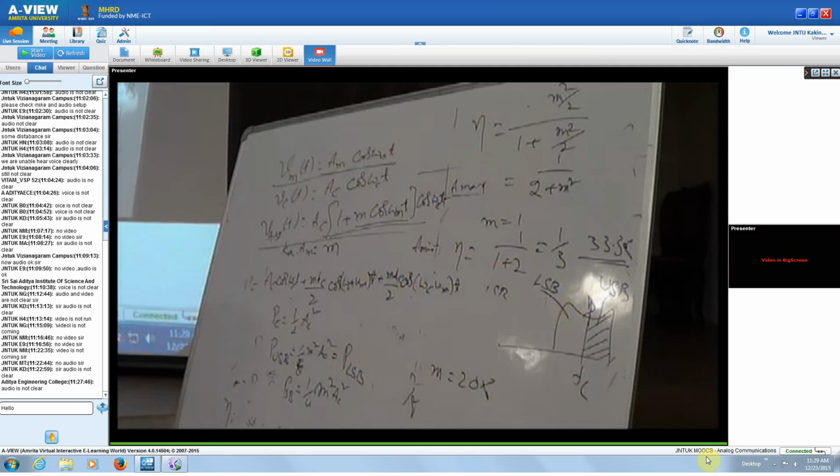The normal modulation index is around 30 to 50% in the transmitted signal. Anyhow, we will see that when we discuss transmitters and receivers. But we never go for 100% modulation, because that may give you more sideband power, but we will have limitations.